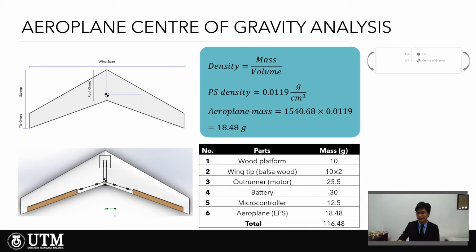So as you can see on the right, that is a square shape. Let me highlight this. This square shape causes the center of gravity to be in the middle, which means that the wing will rotate around the center of gravity. When we put the center of gravity here, it will move forward, which is good. As you can see, having all the assemblies assembled together with the electronic parts and everything, the center of gravity is still in the middle, so this is good.